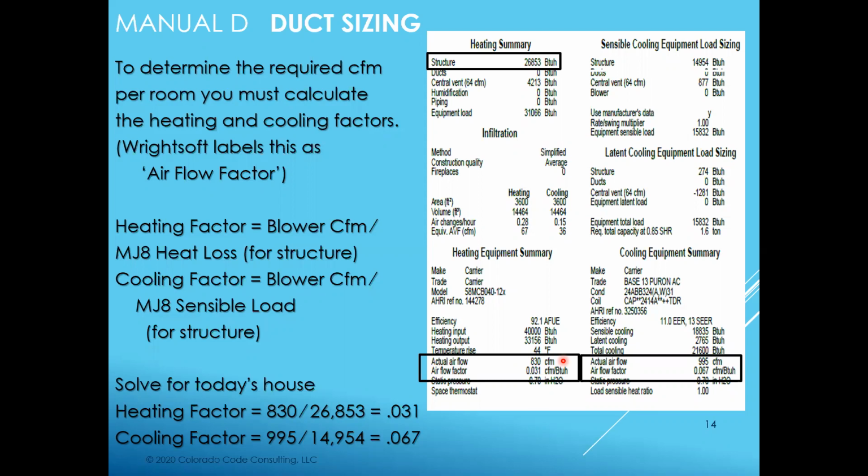Okay, I have not found yet that changing this downstream after all the ductwork's in changes the ductwork design in a substantial manner. You'd really have to double that CFM to make any dramatic changes in the ductwork. Would it change slightly? Yes. Is it going to affect the performance? I would say 99% of the time it would not. It would be in those rare cases where you would have to change it dramatically.